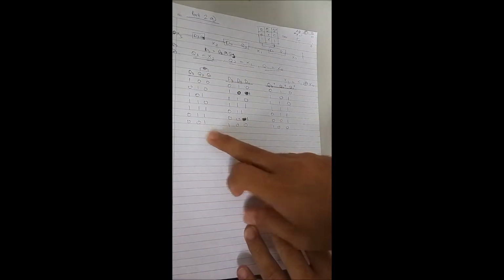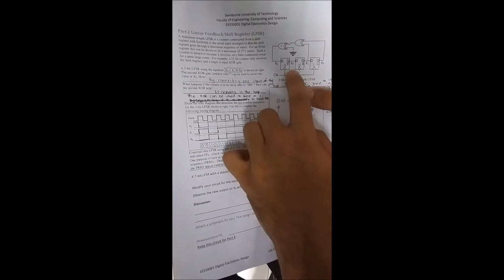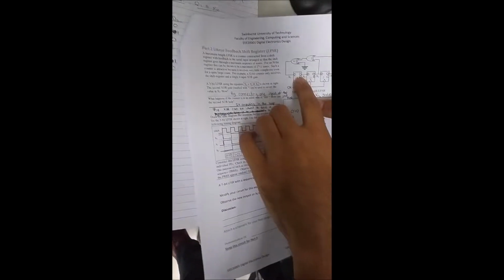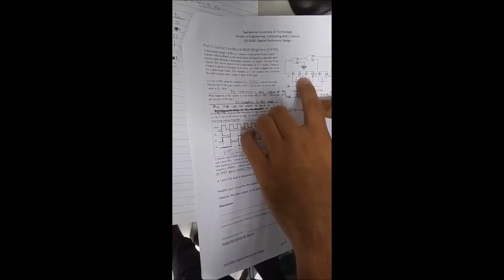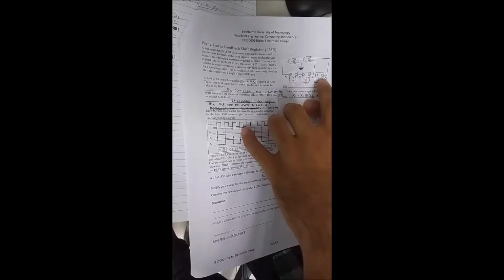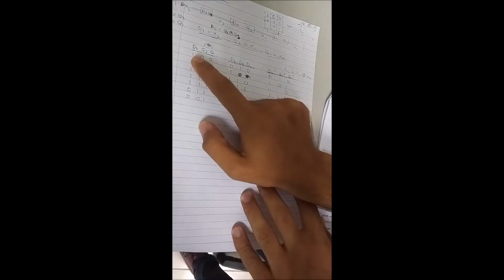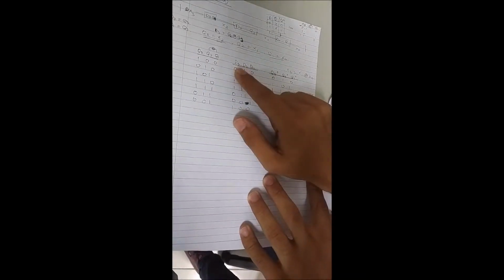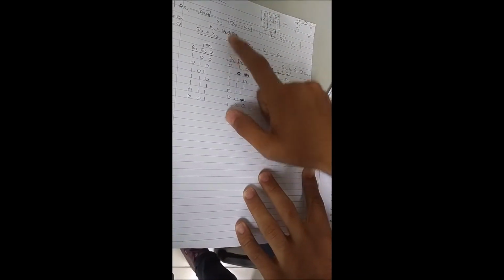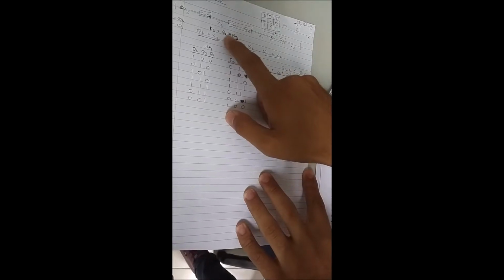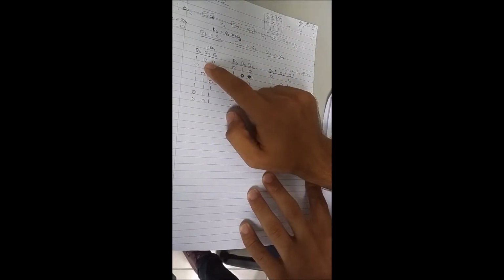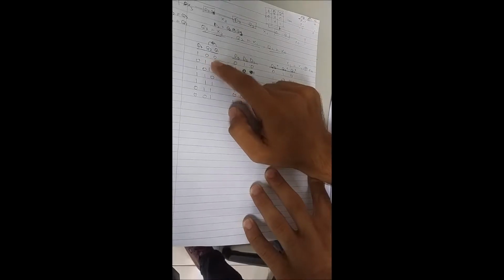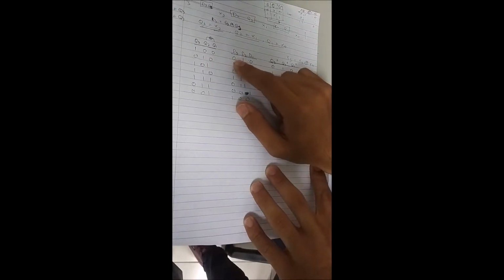And let me explain the truth table briefly here. So this is the present state and this is the next state here. And so from the diagram here, we can see that Q3 is equal to X2, Q2 is also equal to X1, and then Q1 is equal to X0. And this is the present state here, 1, 0, 0. And D3 is the XOR of Q2 and X1. So based on the truth table of XOR, 0, 0 gives us a 0 as well.